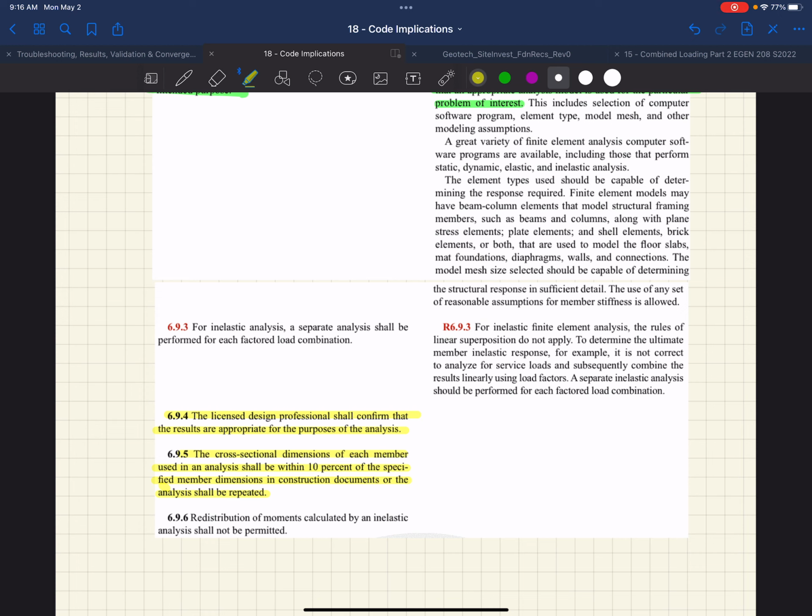But in general, when you start going through modeling frequently and often enough, people have a general sense of what boundary conditions you're going to put on something, right? If it's a very simple moment frame 2D analysis where you just draw 2 columns and have say 2 beams at 2 levels and you apply some loads, they can more or less get through that model and dissect it themselves in probably 5-10 minutes, versus giving a model description, versus something like NAH where now they have 2 different folders and there's 3 different models, and one model combines things, another model is just gravity and another model is just lateral, right? It affords itself to have some sort of description.